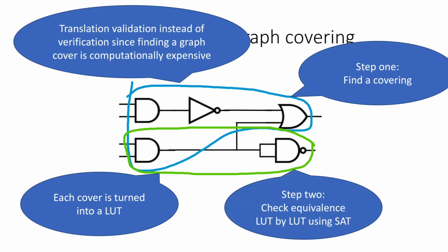Anyhow, to prove the input and output netlist equivalent, we first break down the equivalence problem into a series of small Boolean problems that can be solved by SAT solving, and then, using HOL4 automation, we glue the result returned from the SAT solver back to one big equivalence claim for the two netlists.